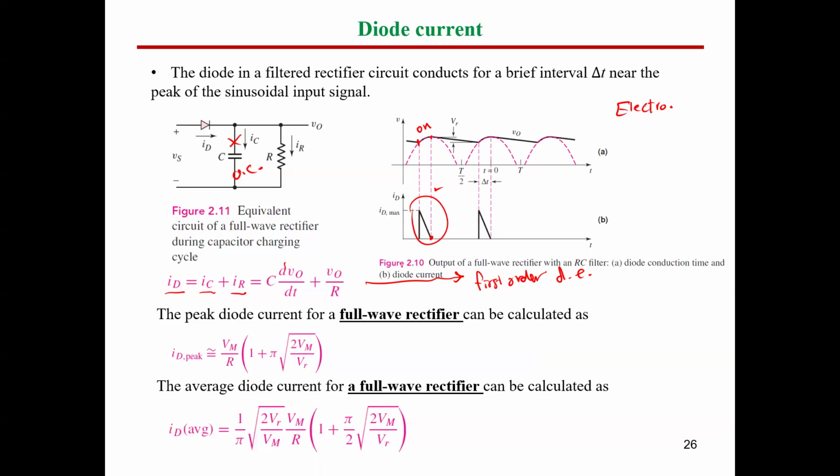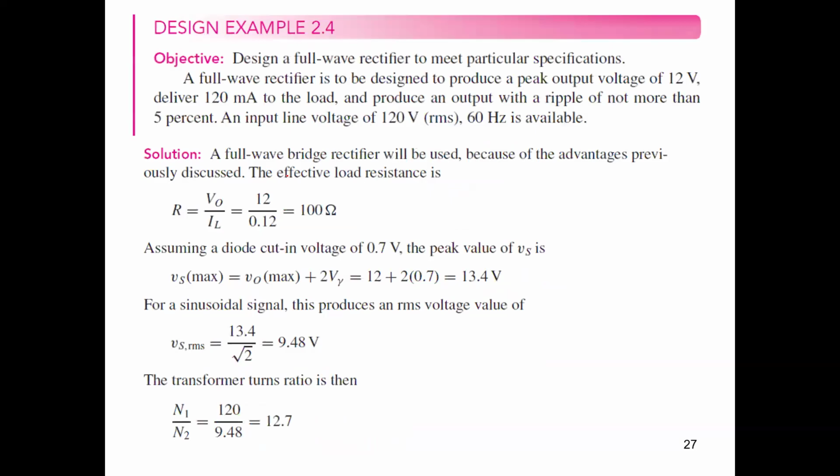So I do prefer not to consider the case we have here, but consider the worst case scenario. So the worst case scenario is I'm going to size the diode according to the main load current. Okay. So this is the concept of the design. And this is what I do prefer to make in such cases.